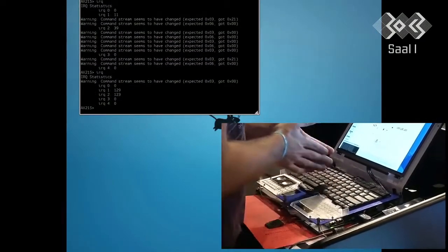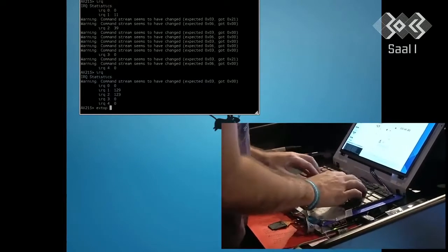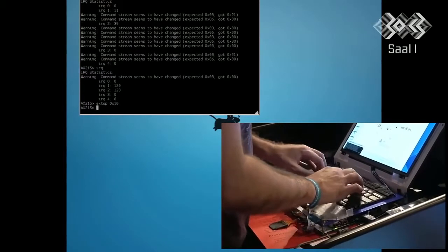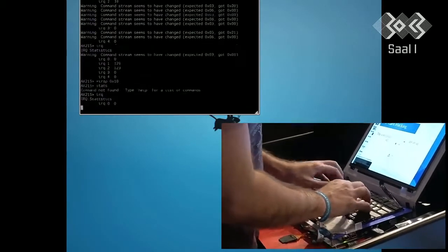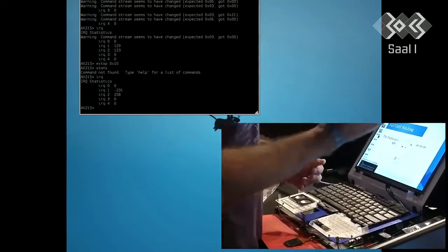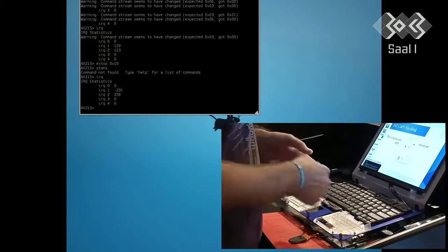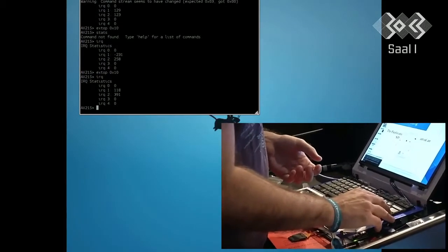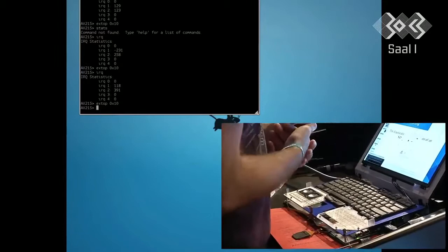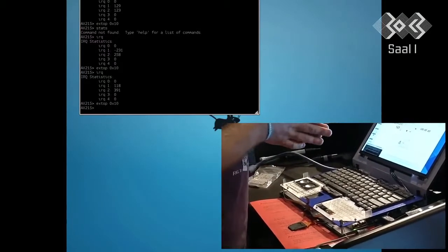Yeah, there we go. So back. You can send X to op and then 1, 0. Stats, it's IRQ. You can see that we now have -1 IRQs. That's because X to op 1, 0 is the invert opcode. And so using this, we can actually fuzz all of the opcodes on the system and basically generally figure out